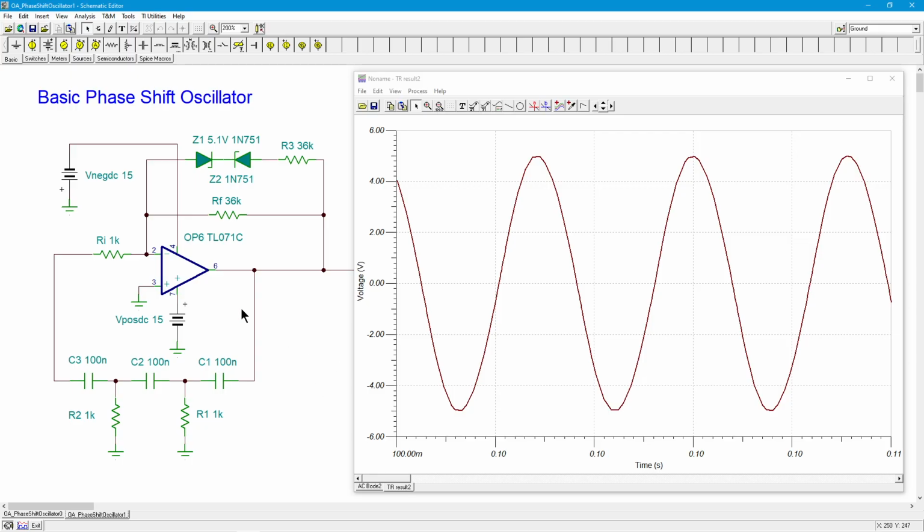But otherwise it's fairly simple. It's straightforward. It's relatively stable. And ultimately it works. It does what you need it to do. It produces a halfway decent sine wave that's just going to sit there, decent amplitude. In this case, like I said, we're getting 5 volts. It's got all the output current capability of whatever op amp you choose. There you go. It's easy enough to calculate new values. Oh, by the way, if you wanted different frequencies, the easy way to do that would be to have multiple sets of caps and use a multi-gang switch.